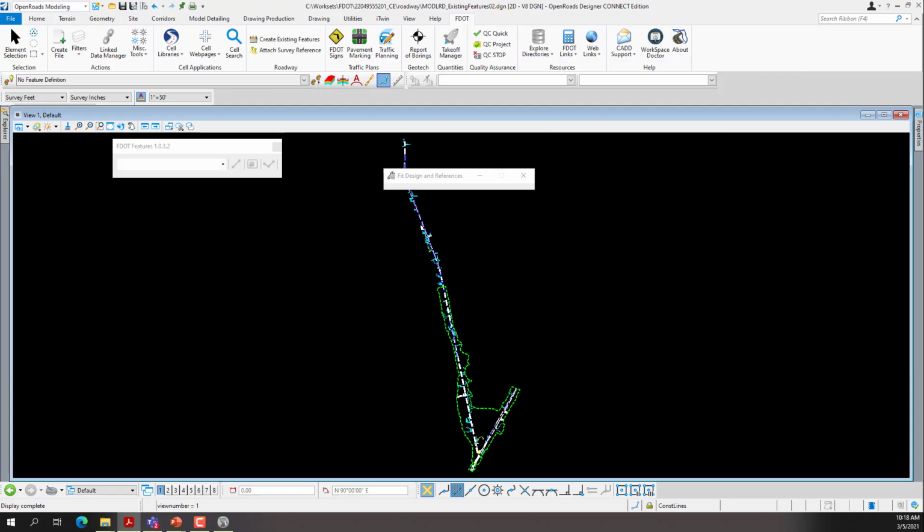The FDOT Features tool will be used to assist in closing the areas and creating the necessary shapes for the existing features to be modeled. The tool contains a drop-down menu and 3 tool icons. The drop-down menu allows the selection of the active existing feature. Levels are turned on and off to help isolate the areas where the shapes are needed in order to create continuous shapes around the existing features. Miscellaneous lines are drawn in the file at the various locations. The first icon, Place Feature Lines.